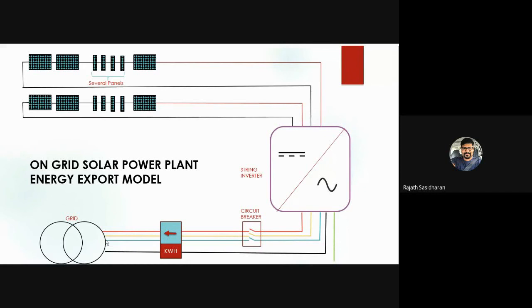These inverters are very smart and sophisticated. The moment any of the phase is gone, it will stop production, because maybe the grid operator may deliberately cut the power lines for maintenance purposes, so they bring down the voltages, and at that point of time, the inverter must not give voltages into the grid, right?